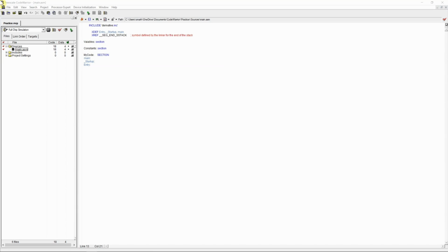Now to begin, in the previous video we wrote this simple instruction LDAA, and then we followed it by the pound sign, and then we wrote our number here, whatever that number was, 4, 3, 5, that number doesn't matter. Because we have that pound sign in front of the number, we can identify that this is an immediate addressing mode. It is called an immediate addressing mode, and what is happening is A is being equal to that number that we just wrote.